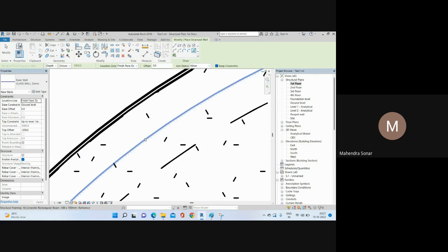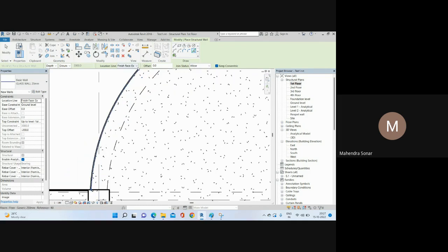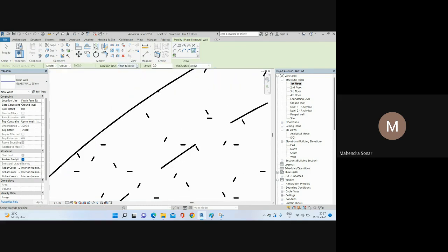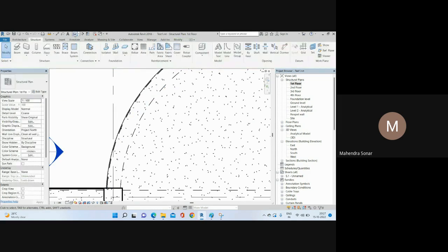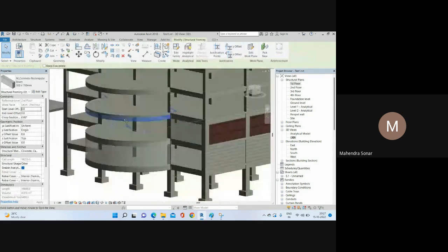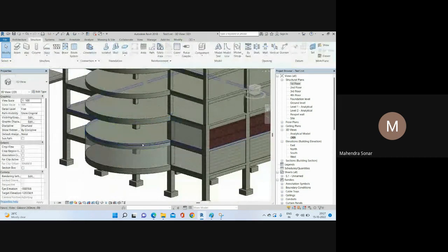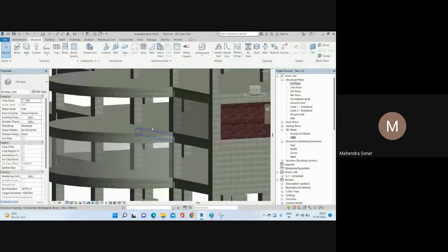like that. But this is your outer face, so we have set, just change here. So make it undo, and instead of exterior you need to select interior and select this. So you can see, if you look at in 3D view, there is your wall. So yes, this where we have added, yeah, so there is our glass wall.